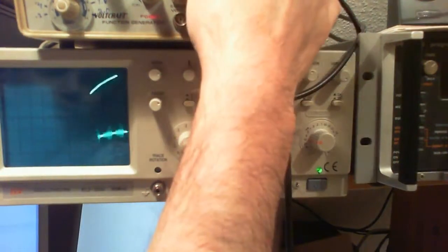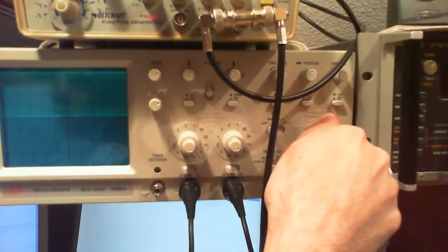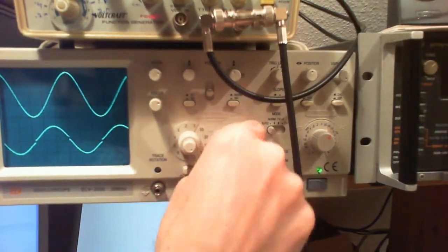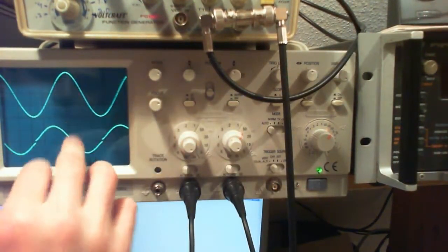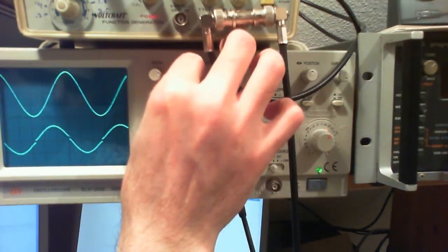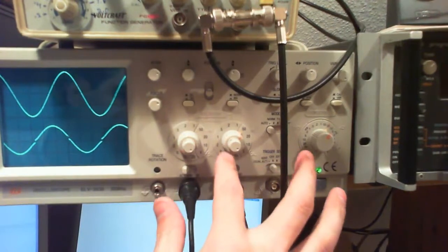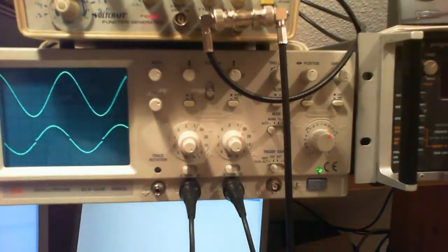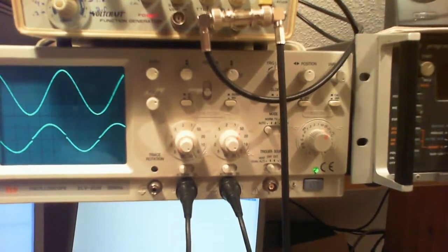So I increase the frequency, and now I can read the output voltage peak to peak, and that's about, so I'm at 5 volts, so 1, 2, 3, 4, 4.8. So 4.8 times 5 is equal to 24 volts peak to peak or so. So my input is at 24 volts peak to peak,